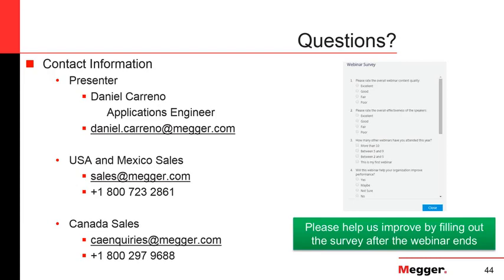But it's also important that if you move either one or two of the leads a little bit when you are connecting those to your specimen, you have different readings, like we saw in the diagram. What the tester will do is measure the voltage drop between the 2 points where you connect the potential leads. So if you move, let's say, only one of the leads, you are changing that distance, and that's why you also see a different resistance value.